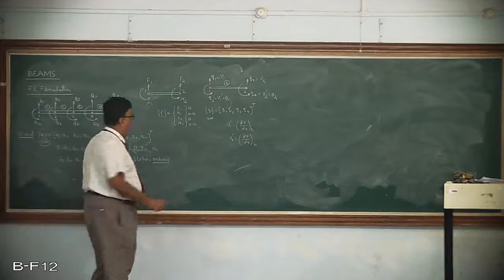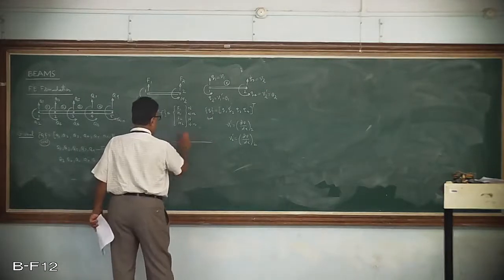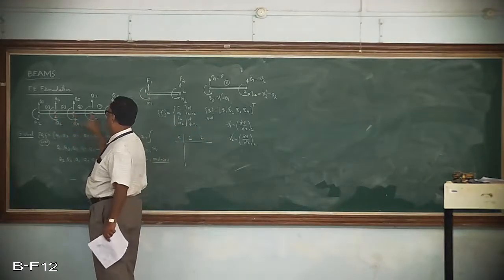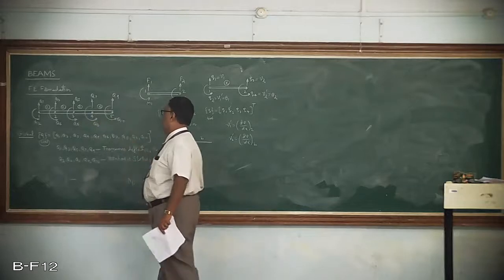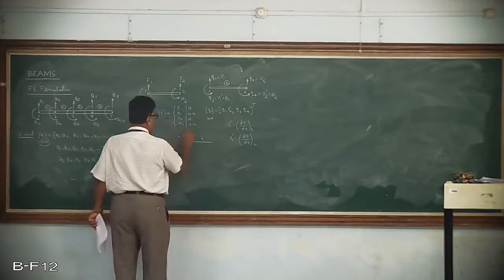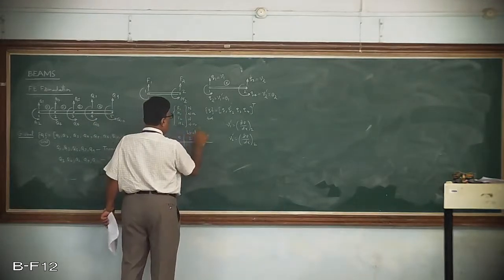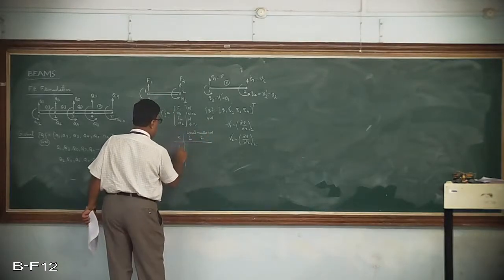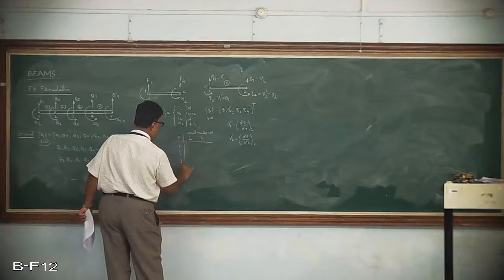So if I want to connect the mapping, for example, if you look at this figure, the local nodes are 1 and 2. Everything has got 1, 2, 1, 2, like that. These are the local node numbers. And there are totally 4 elements in your case.